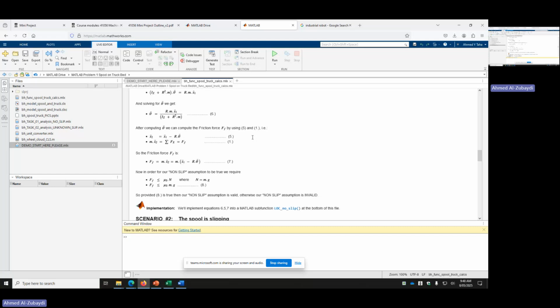And the quality assurance is always going to be done by a process called SPC, which is statistical process control. I will give you a hint about that. I mentioned the 6 sigma as an example, where you calculate the sigma, which is the standard deviation, and your acceptable range should be between minus 3 sigma and positive 3 sigma, which is in total 6 sigma.